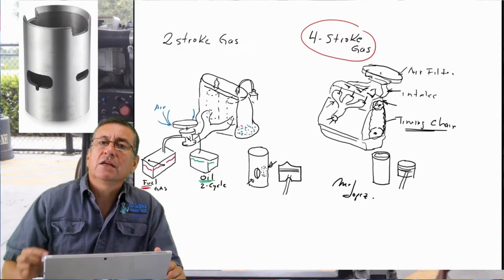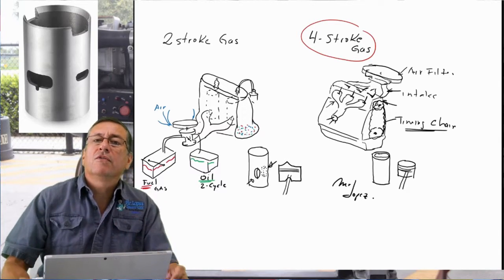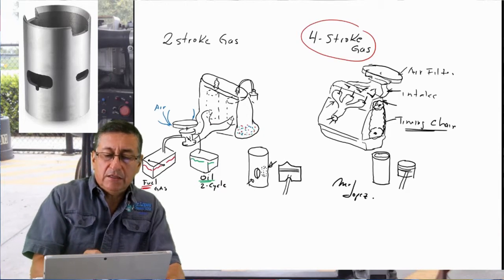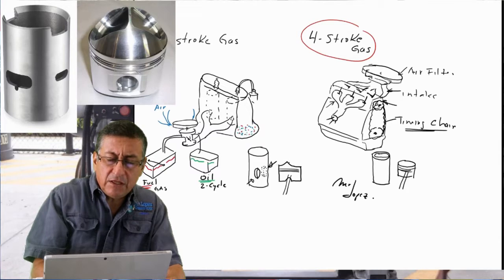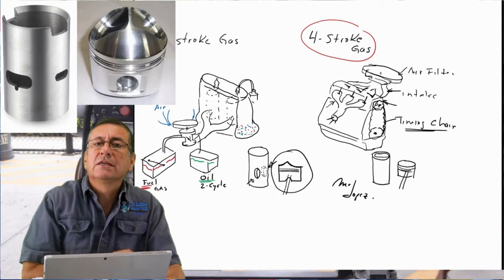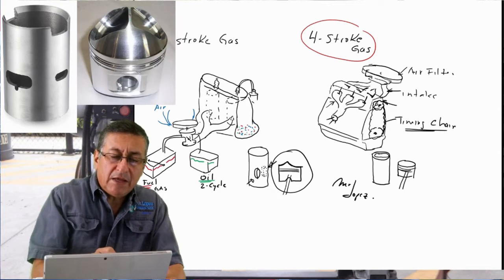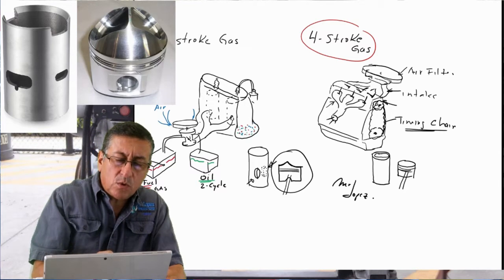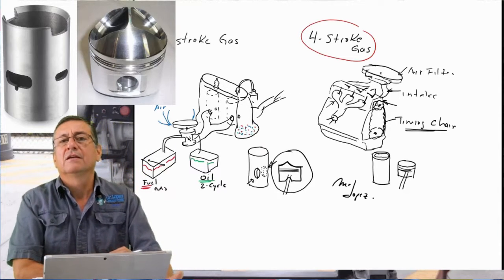In the bottom of the cylinder, if you check the picture, there are 2 holes, one practically in front of the other one. And additionally, the shape of the piston head in 2-stroke engines has this shape, like a castle, like this. And what is the idea? In the bottom of the cylinder, there is a hole here and another hole on the other side for exhaust, because the exhaust manifold is located here on the other side.